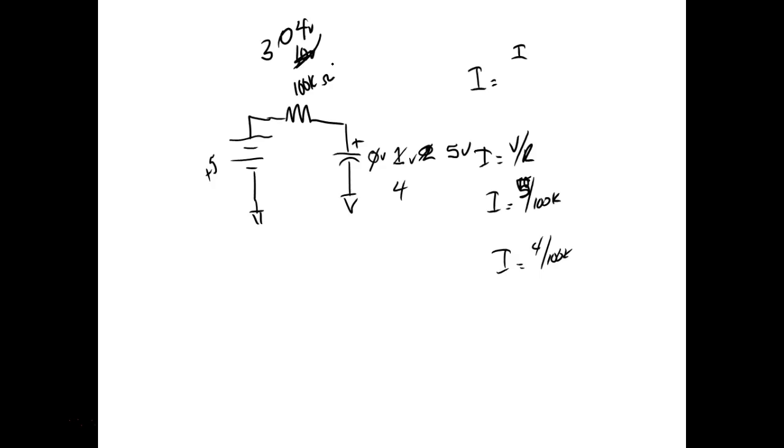So a capacitor in a DC circuit, when it's charged, it acts like an open. When it's charged, right? You understand that? And if it doesn't have a path to discharge. So what we're going to be able to see when I put my meter across this thing is, when I put power on this thing, making sure I use the right polarity.